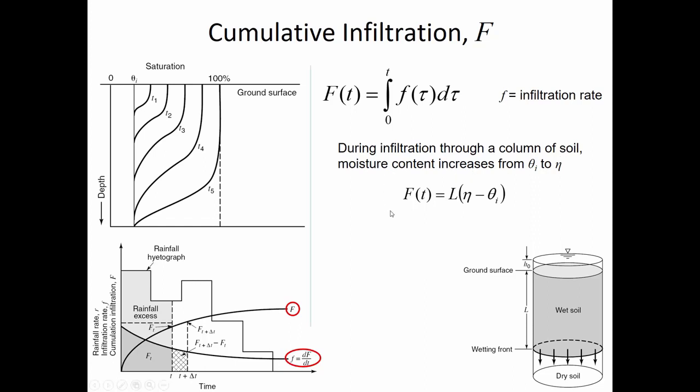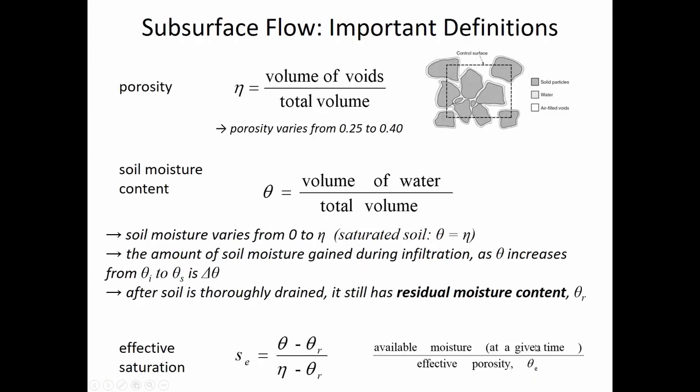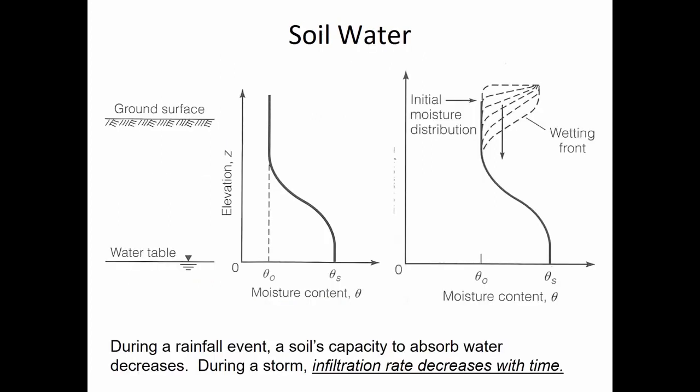But I just wanted to point out that the penetration depth is not the same thing as how much was actually infiltrated. Just because it's a matrix, if we go back to that figure, to begin with, there is solids and some initial water. So the volume that's filled with air initially is the only place that the incoming water can go. And so if we have 1 unit of water, it's going to infiltrate much deeper than 1 unit of depth.